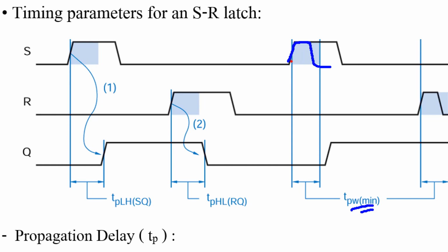but not so much. Namely, maybe around right here, the value of Q may be changed. If it changed to around 2.5 volt, what happened? If your input is back to 0, when output Q tries to go up from 0 to 5, but it does not reach 5, your input is back to 0. Okay, it becomes bistable, right?